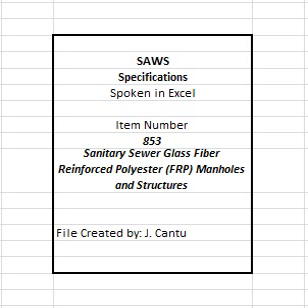Approved manufacturers, as listed in the SAWS APL, have previously completed required inflow leakage shop testing and have met a maximum allowable leakage rate criterion of 1 gallon per minute, GPM, at 12 inches of water submergence above the manhole cover. The nominal cover diameter shall be 32 inches, with a 30-inch clear opening, as required by TCEQ.